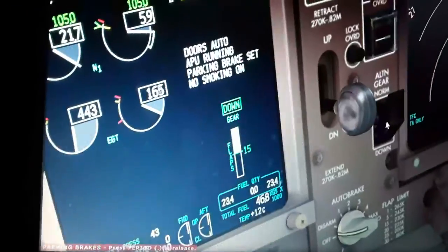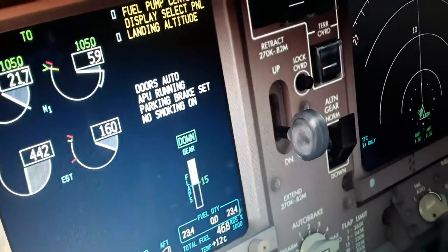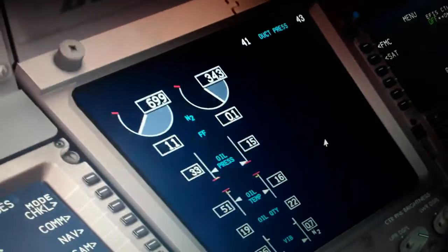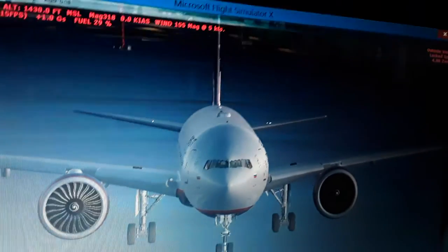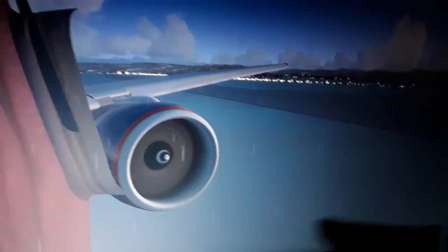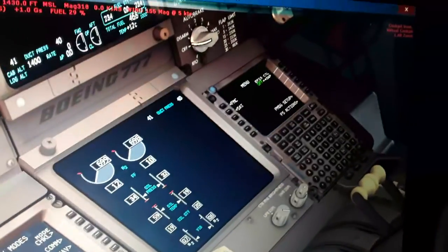So we can let this right wing engine now have fuel flow. As you can see, the N1 is gonna increase rapidly also. So is the fuel flow now. It's going up. So we have the right wing engine now on start. You can see here the spinner going higher and higher, the right wing engine. And here we are, fully started. We can now complete the last part before takeoff.